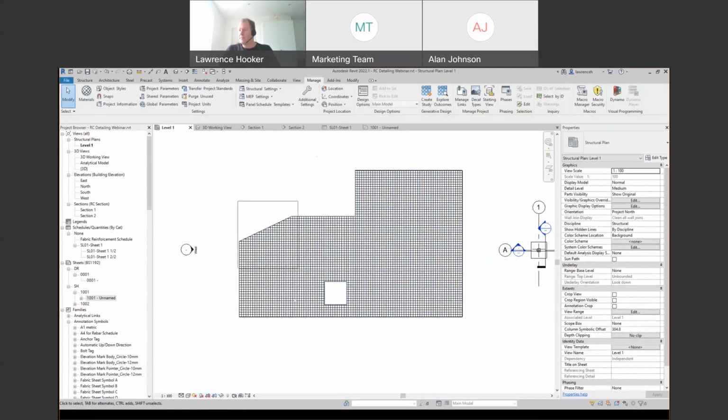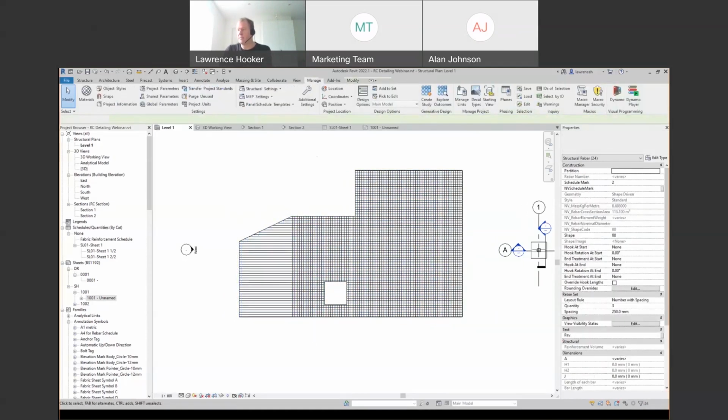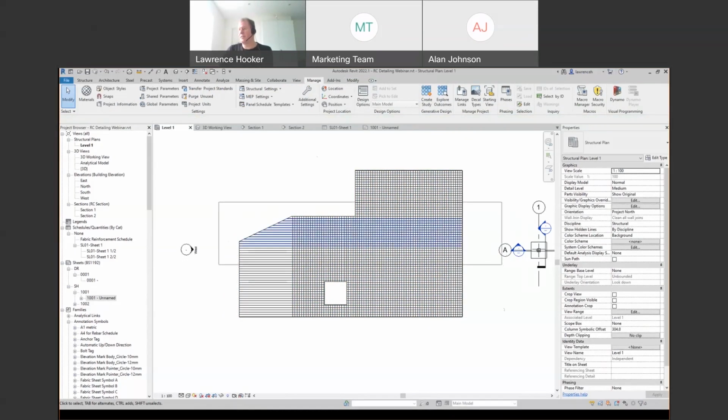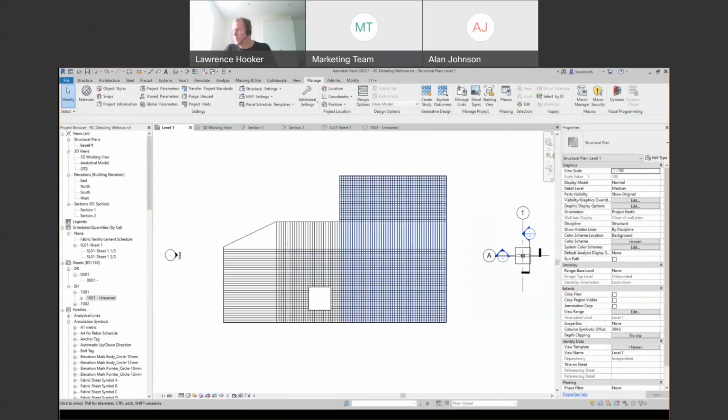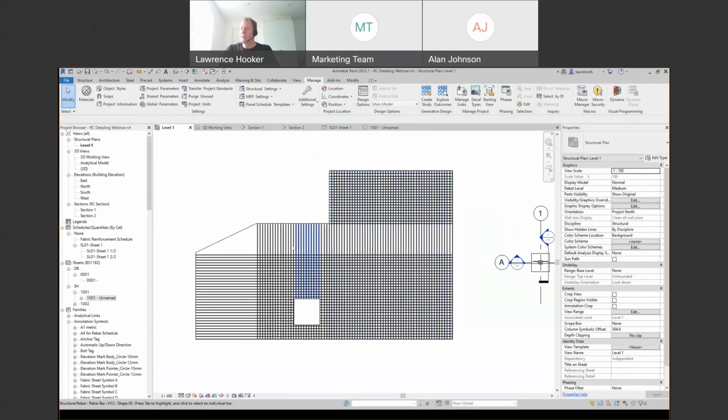Now, a couple of things. I don't want these bars in here as loose rebars. I want that to be a varying range rebar set. So I'm just going to delete those, and you can see how easy it is to do that. Just sort of sweep a window around it and it's done. What we can then do is start to think about the subdivision of all of the reinforcement bar, okay?